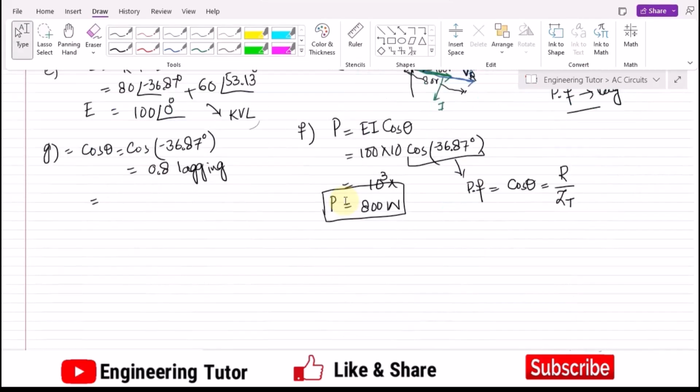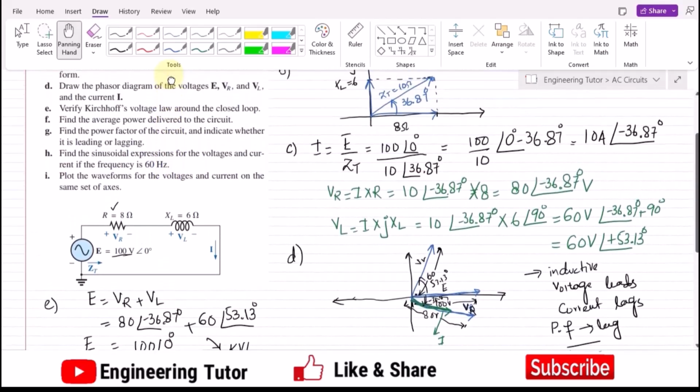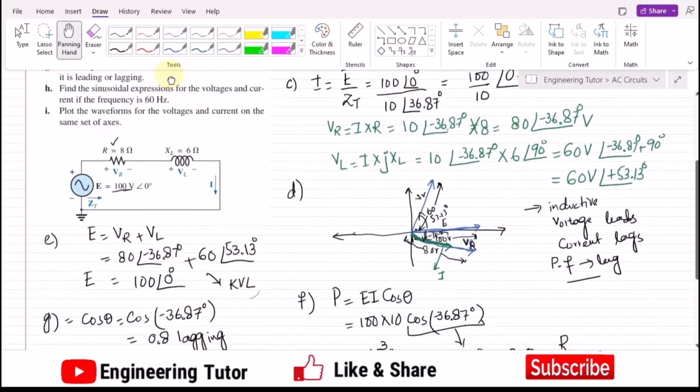Apart from it, as I have told you, power factor is also equal to R divided by Z total. The value of R is basically 8 here, because you may see from this circuit the resistance is 8 ohm, and the magnitude of the total impedance we have calculated is basically 10 ohm.